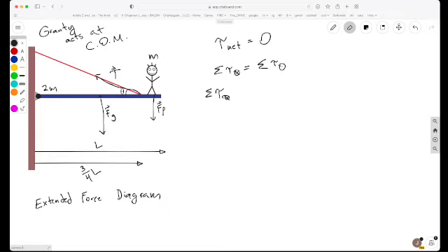But now it's helpful to spread them out because we found out that for torques, it matters where the forces are, right? The radius, or the distance from the axis of rotation to the application of the force affects what torque will be created. So we do care about this. So we'll be going back and forth between these extended force diagrams and the other type, which I just drew, called a free body diagram. We'll do that for this example a little later on. But for now, let's stick with the torques.